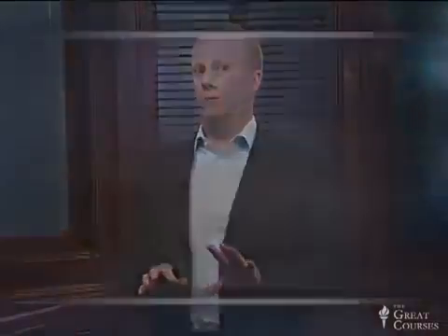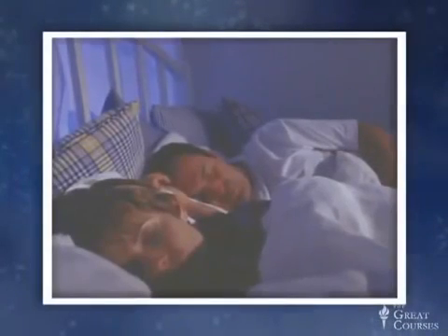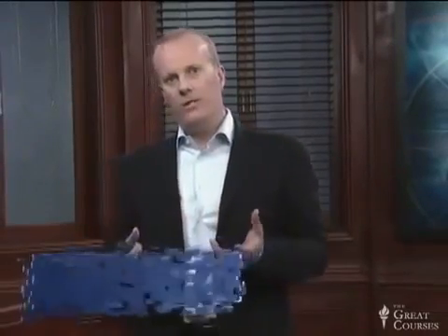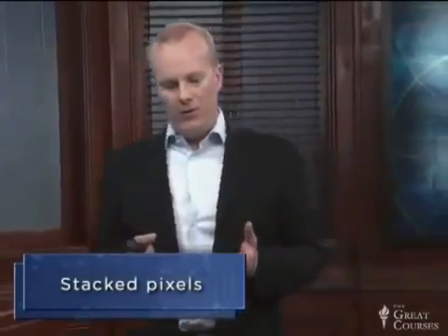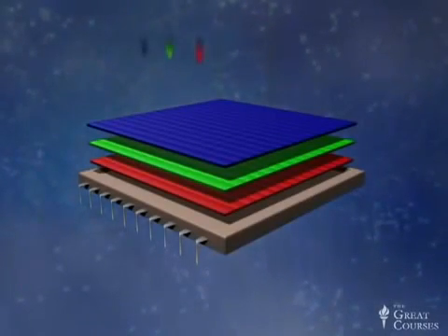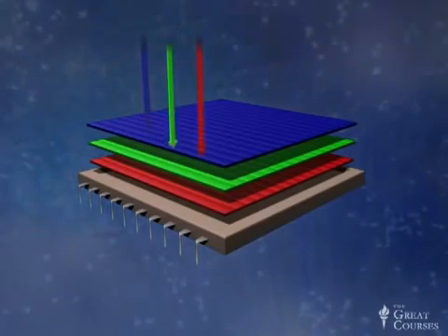And when we're light-starved, when we're trying to take an image in very low light, that's a regrettable thing to be doing. Now, what quantum dots and nanomaterials enable, through their wide spectral tuning and the sharpness of their cutoffs, is a new strategy called stacked pixels, wherein instead of using filters that first throw away light, followed by sensors that sense all colors, they enable the realization of a stacked pixel in which a first top sensor senses the shorter wavelengths, the higher energy photons, and it detects them there.